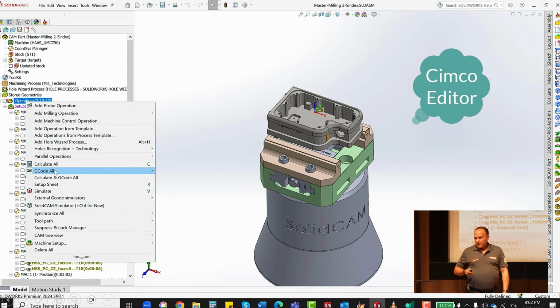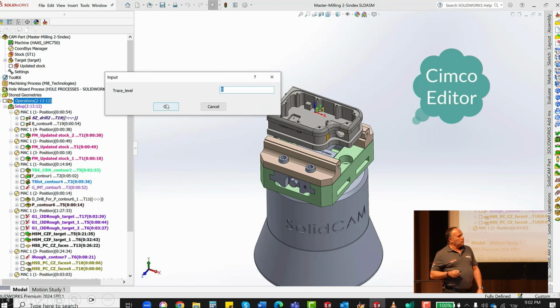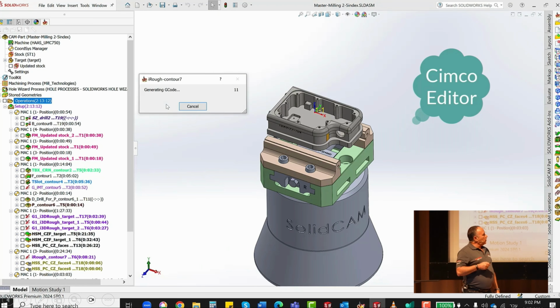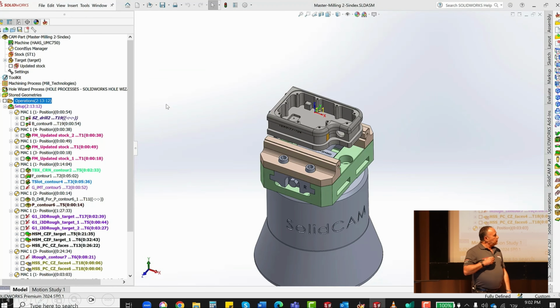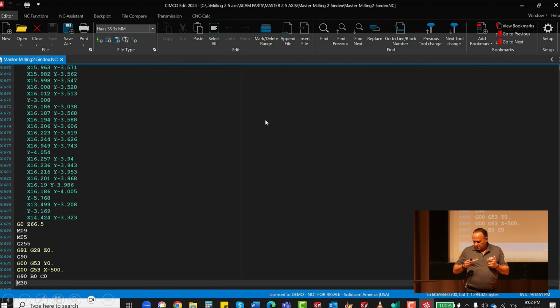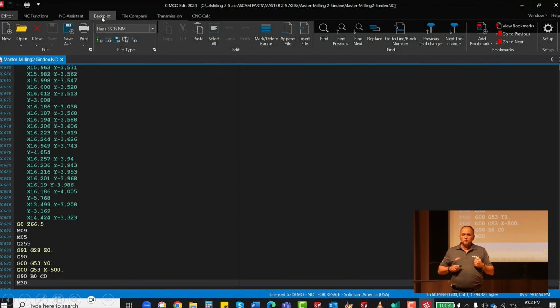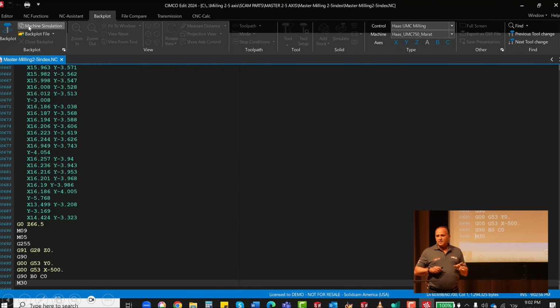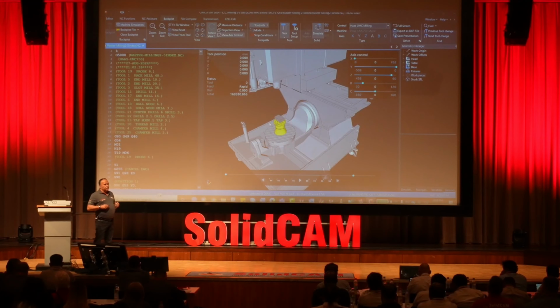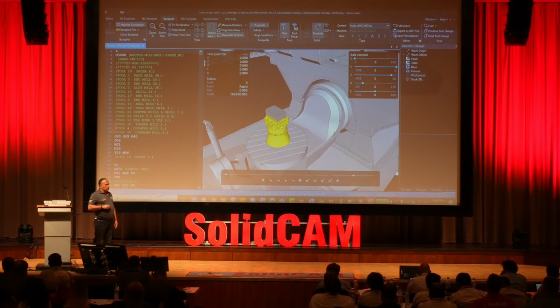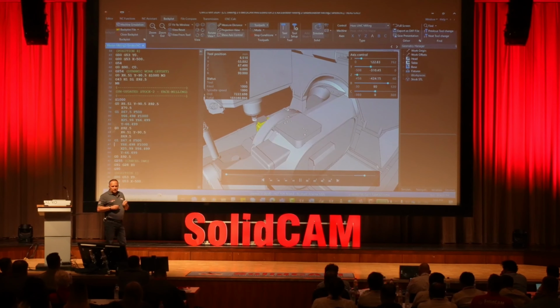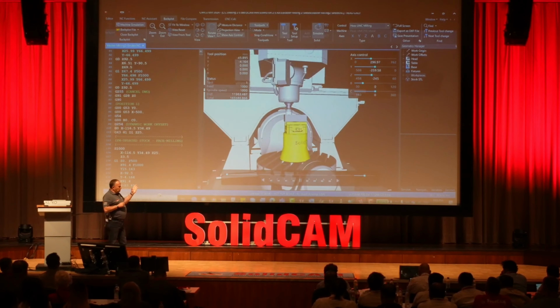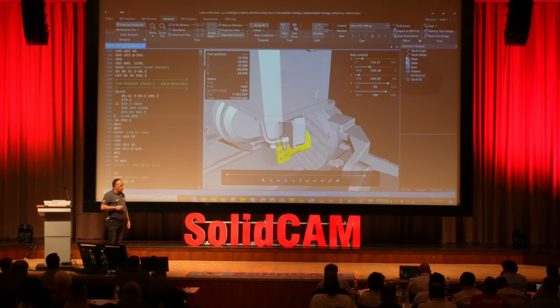And it's also a very, very nice simulation of SolidCAM with a lot of other benefits. And now we have also another tool. It's a Simco editor. So when we generate the G-code, automatically we can simulate the G-code, because the customer doesn't all the time understand. They think if we run the machine simulation, it means it's 100% safe. It's not. So if they want to be sure that there is no problem in the part, they need a G-code simulator. Now that we have the Simco editor, we will have also Vericut.